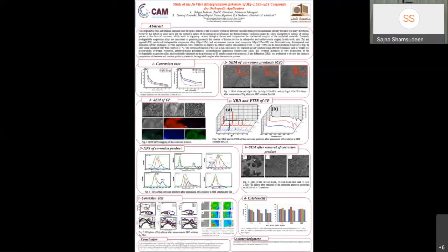Figure 3 shows different morphologies, such as nanoflakes and needle-like structures, found in the corrosion product of all magnesium samples, composed of calcium, magnesium, zinc, and phosphorus, as illustrated by the EDS mapping after immersion for 28 days in SBF solution, indicating the possible existence of magnesium and calcium phosphate in the corrosion product, which is the main composition of hydroxyapatite.